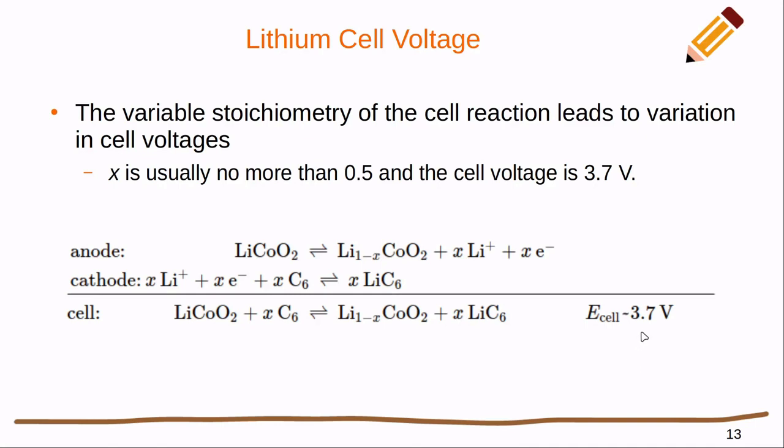And what you can actually do, we'll talk about it later, but if you had 1.5 volts, then you're going to need 2 cells in order to get it to 3 volts. You're going to need 4 cells in order to get it to 6 volts. And you're going to need 8 cells in order to get it to 12 volts. But this being roughly 4 volts, you can get close to 12 volts with 3 cells. And so you can often see combinations of these types of cells that are operating 12 volt devices.